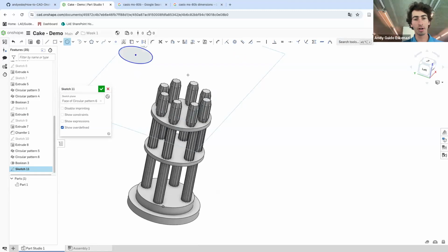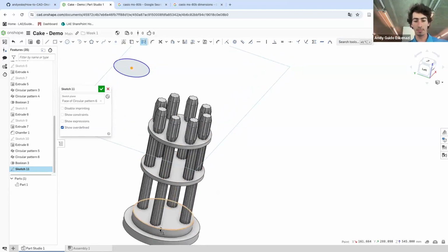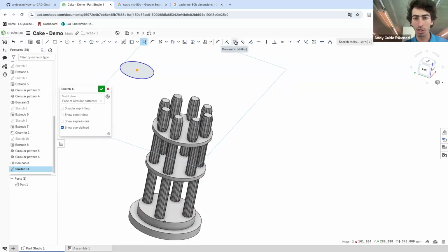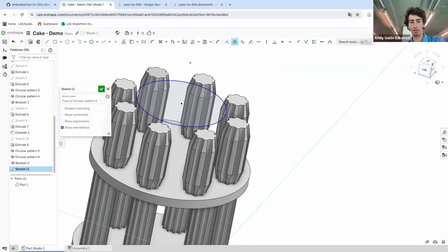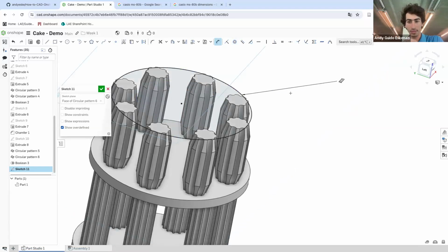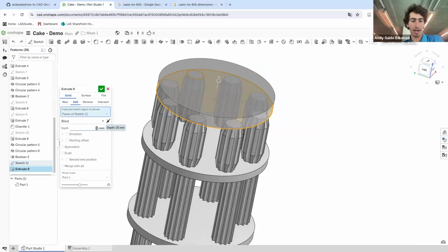We'll do a circle. And another way, I've been using the one where I make these 2 points, that one and that one, be coincident. Instead, I'll do another one, which is I can make things concentric, which is I can click in this circle, I can click in that one right there, and you can see how it's brought. Yeah, so that's another way of achieving the same thing. So you can click now in D, and I'll make this one 220 instead. Actually, maybe a little bit more. Very good. And now just an extrude by 15.